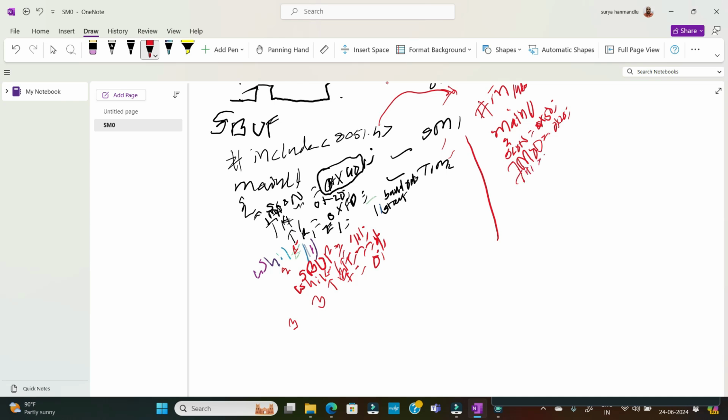Then we have to select the baud rate. At what rate the data has to be received. So here also, we can write 0xFD. As I promised, I will tell you how to set the baud rates, whether it is 9600 or 4800 or 2400, like that. For each one, we have a value. Or simply you can put directly -3 also here. Okay. FF, -1 is FE, but there is no baud rate for FE.